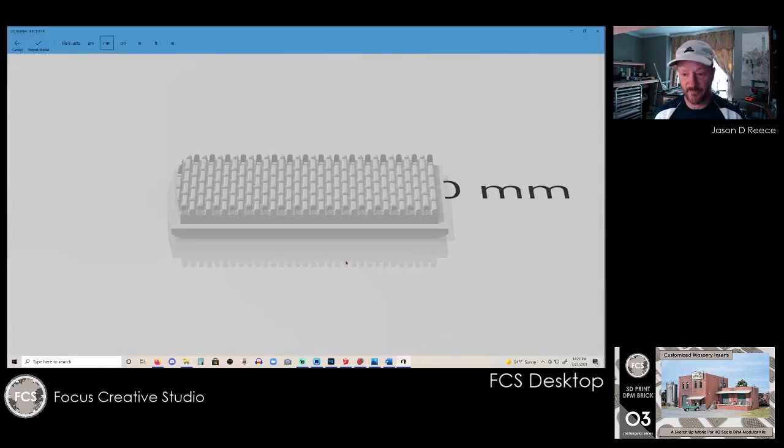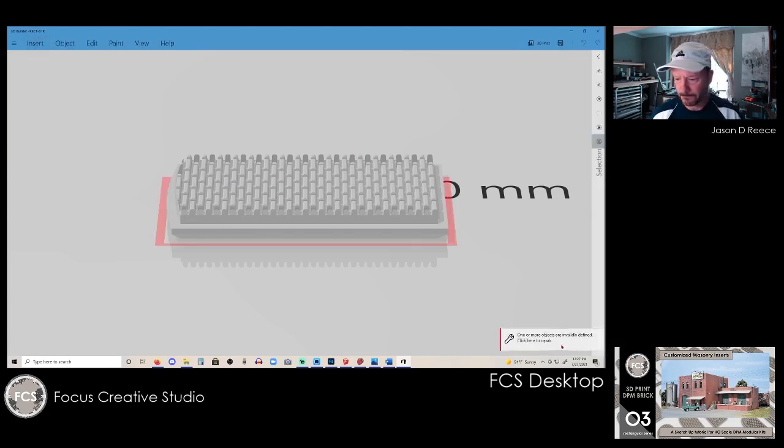And now, immediately before I rotate or do anything, you can see I've got these dark faces. Those are flipped faces, or what's called flipped normals. In the model, they didn't show up as reversed, the darker blue like the back. But when you flip a group, it will automatically flip these normals in the STL file. It's just an inherent hurdle with SketchUp, and there are a few other programs that this happens with as well. So what you want to do is import the model, click to repair it, and you'll watch them flip.